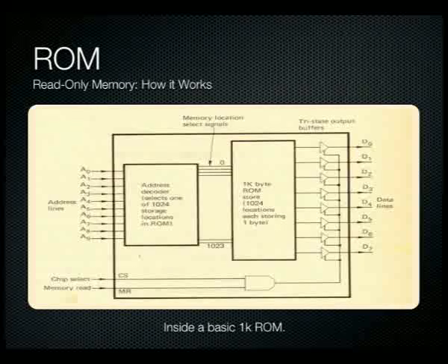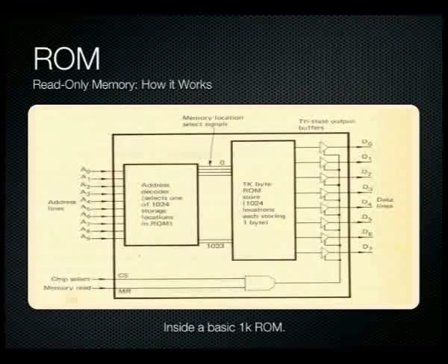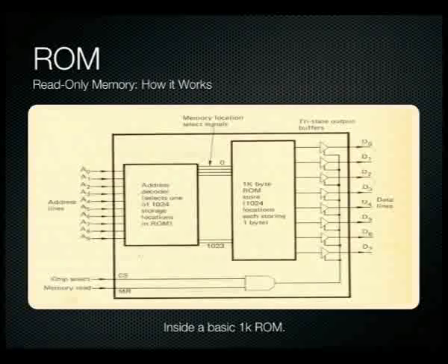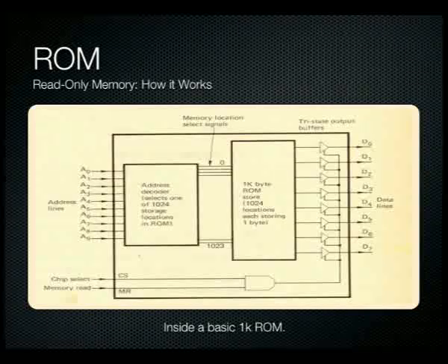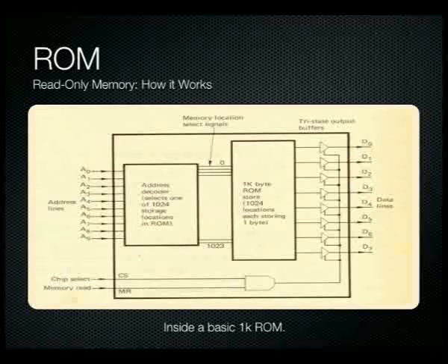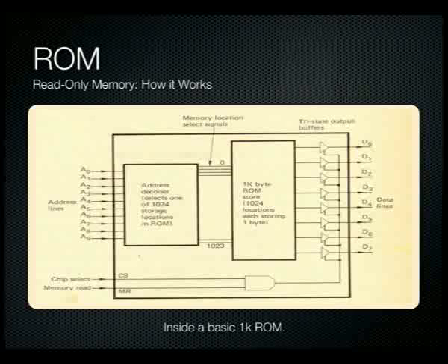So those 1024 activation lines will then effectively connect into our memory elements. Okay, so we have our memory elements in which we have rows and columns of memory elements. I'll get back to that in a bit more detail later on. And then coming out of that two-dimensional array of memory elements, we have it connected up to the data bus through a series of output buffers.